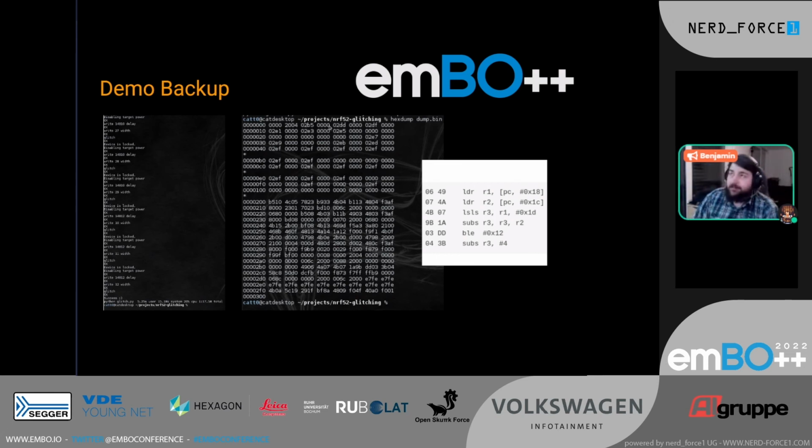So the next entry is the location of the reset vector, which is the address of the first instruction that is going to be executed. So 0x2B5 sounds good. It's fairly close to the beginning, and we know this is a small firmware. So let's search for 2B4, because it's always +1 due to Thumb mode. And let's just disassemble the first few instructions. If you throw it into an online disassembler, we can see it decodes to the usual things you see in the beginning of the execution. You load some constants from memory, you do some operations on them, you do some branching on them, and continue on. So, yay, glitching worked, even though the demo gods are not in our favor today.